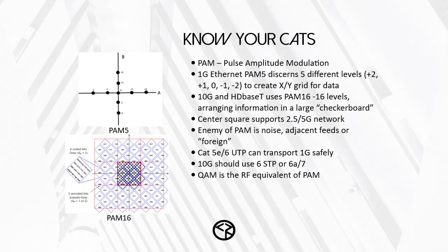However, you'll notice that Crestron, when they sell their cable, is always providing cable that is shielded. 10 gig should use category 6 shielded or 6A or 7 cable. The difference being is that category 6 shielded has a foil around standard Cat6 cable. In 6A, the individual pairs are also shielded, so within the cable the pairs are shielded from themselves.